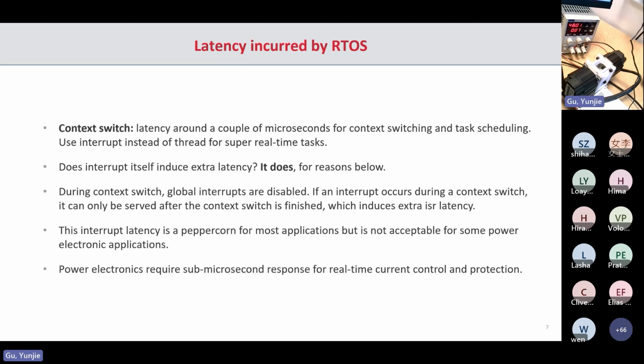It takes some time to save the context, run the scheduling algorithm and switch to another context. So people ask, why not use threads, just use interrupts. Of course, you can do that, but even for interrupts, you still have latency introduced by the RTOS.